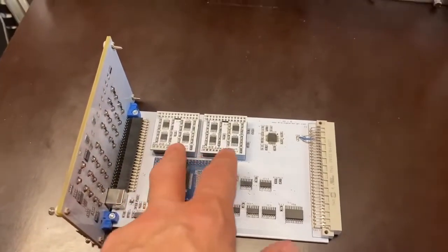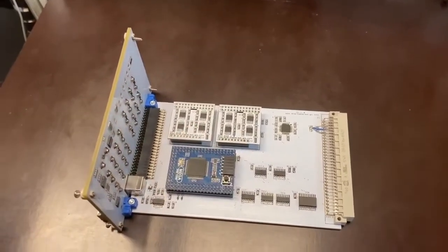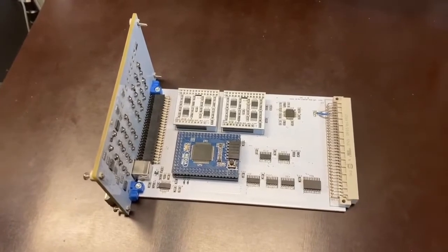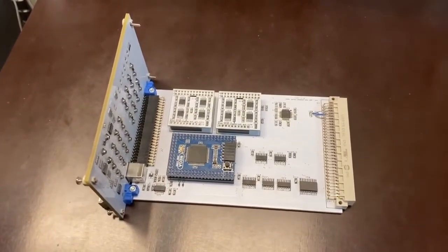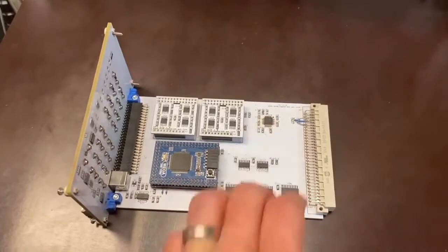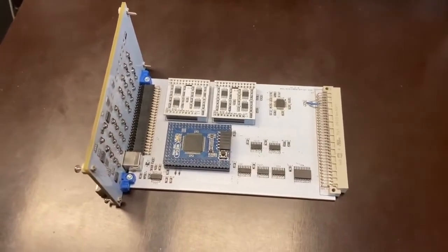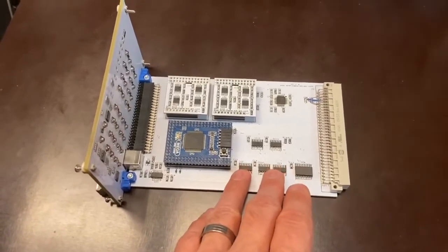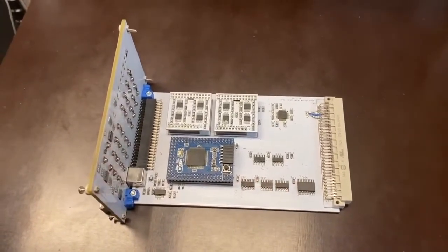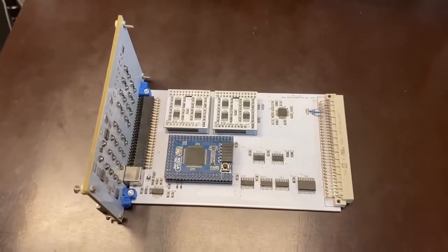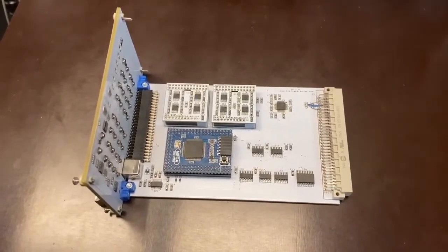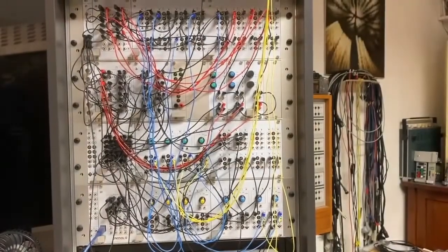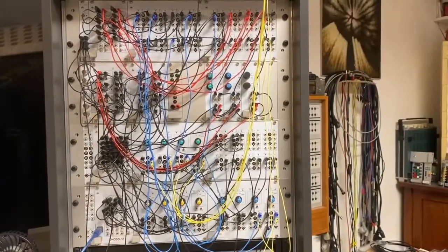What you see here, these two modules, is our in-house standard, so to speak. These two modules contain 4 digitally controlled potentiometers with 10 bits resolution each. Here you have a 16-bit precision analog digital converter, and you have a little bit of digital logic, which is required to select any of the computing elements being part of the computer setup to be read out by the analog digital converter.